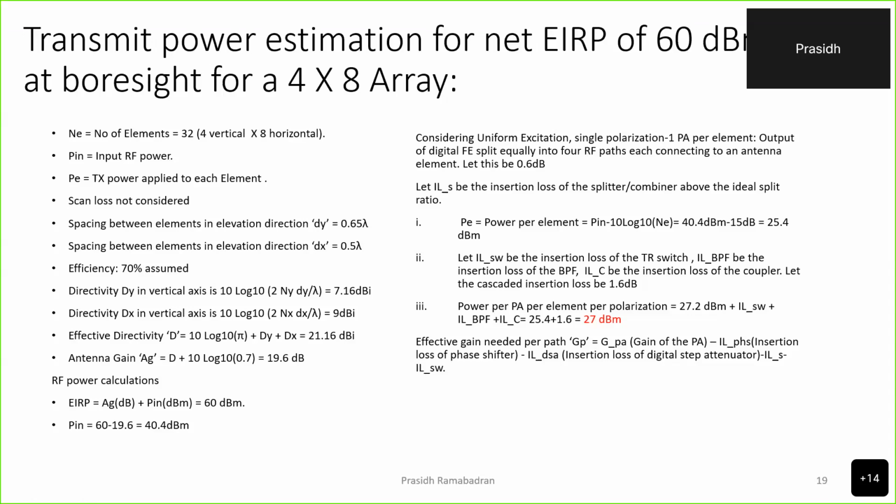Now, directivity is not the gain, because directivity is how directive the antenna is, or the ability of the antenna to focus the beam in a specific direction. But the antenna is also made up of practical elements which are not ideal. There are going to be things like dielectric loss, the feed loss, perturbation in the conductor, surface waves, etc. So typically, for a planar microstrip array, one could usually get an efficiency of, say, 70%.